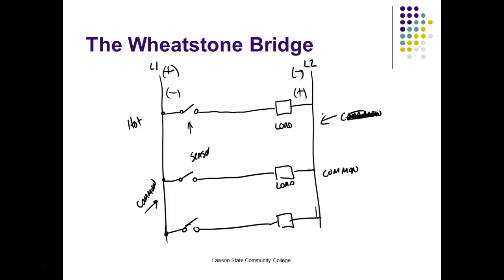When we use a negative common in digital, we refer to that as sinking. When we use a positive, we call it sourcing, and a negative we call sinking.